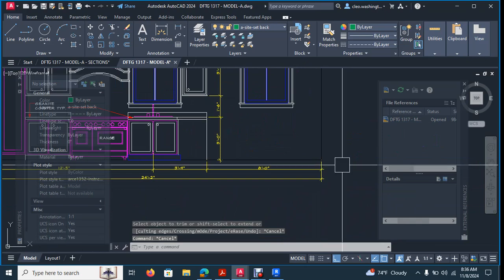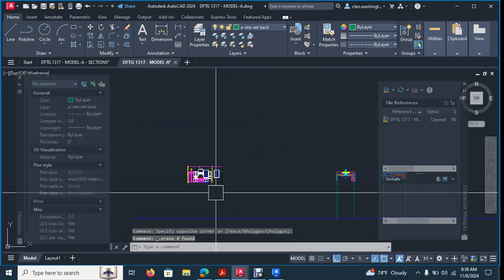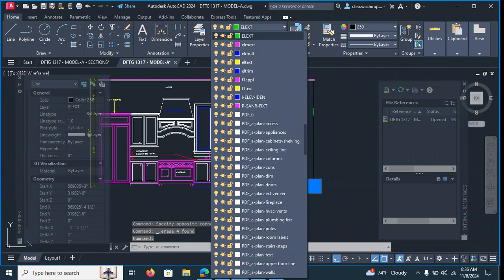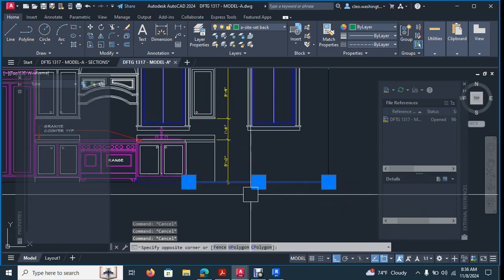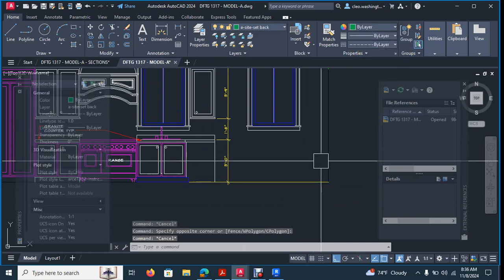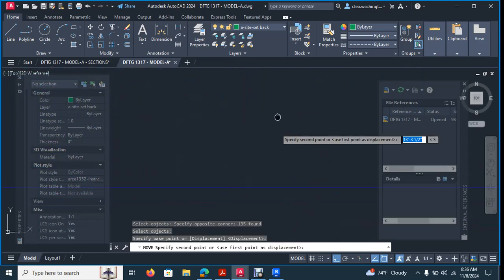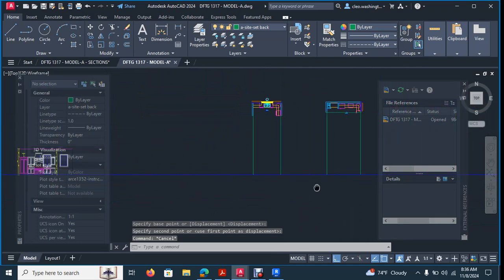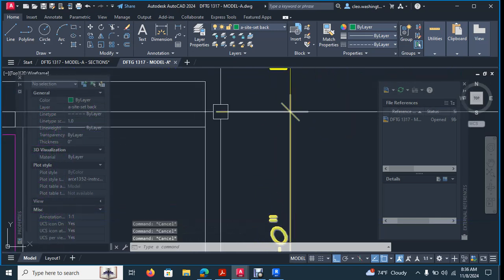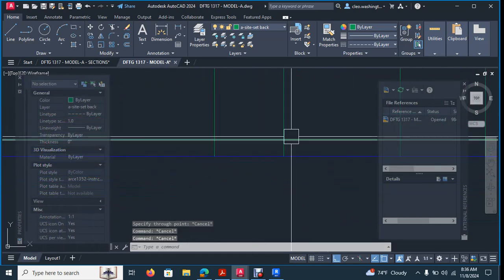And let's take this guy. Let's delete the elevations dimensions at the bottom. And this is our floor line. Let's put it on a layer that can actually be seen, if it will allow us. Oh, change the color. The color is set to 250. Let's change the color to by layer. Let's move this line down. All right. And this is the kitchen counter. So let's project this line over. And we all know that that counter height is 3 foot. So that's our starting point.